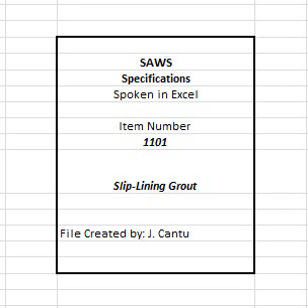This procedure is intended to ensure that the grout is not diluted by extraneous water in the annulus. 6. The drilling of additional injection holes from the surface to facilitate grouting may be allowed, if approved by the engineer. 7. Upon completion of slip lining, but prior to grouting, bulkheading of the ends and appropriate venting shall be required. This is to seal the annular space from sewer flow to permit the grout to set and withstand the loads imposed by the grout and groundwater.